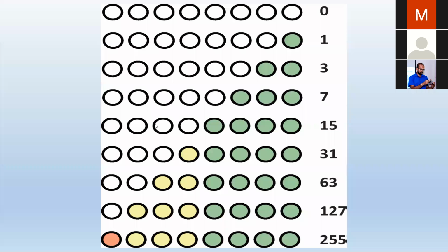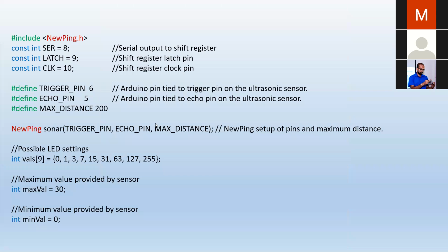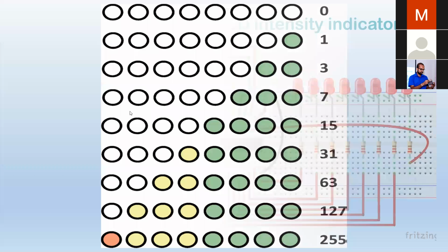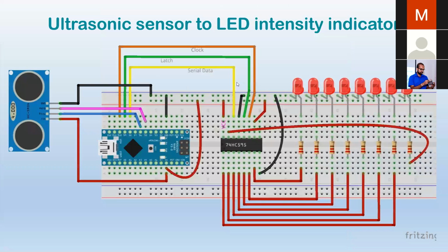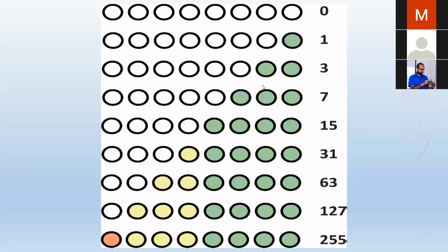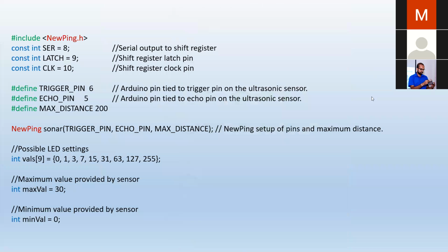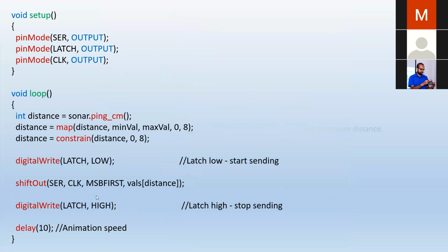So this is how you use that and the shift register, right? It is a bit complicated example, so we don't waste 8 pins for LEDs, but only 3 pins to send out the data to the LEDs, and we can even use 16 LEDs and still use 3 pins on the Arduino. Like that, there are nice things you can do. So this is how you control displays.